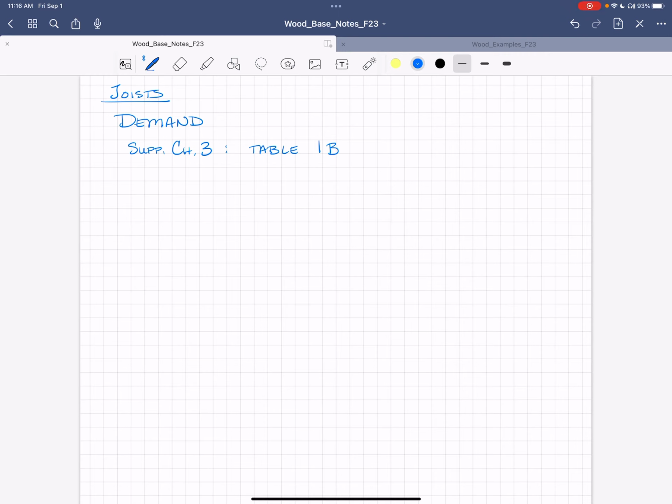And we're in the sawn lumber example section, so that's what we've got. If I go into that table, it'll give values for each of the dimension sizes. If I look at a 2x8 in that table, 2x8 dimension lumber, and go across, it's going to give me the standard actual dressed size. Say for a 2x8, it's 1.5 by 7.25. It gives me the area.